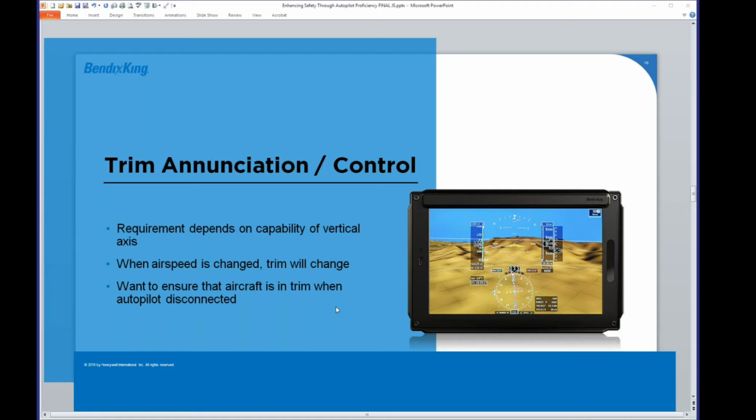In the AeroCruise Autopilot, in the certified product, we don't currently offer automatic pitch trim. We do have trim annunciation in that product, obviously, because we are commanding climbs and descents. In the X-Cruise, the experimental version of this Autopilot, we do actually offer automatic pitch trim, with plans to add it later on down the road for the certified product.